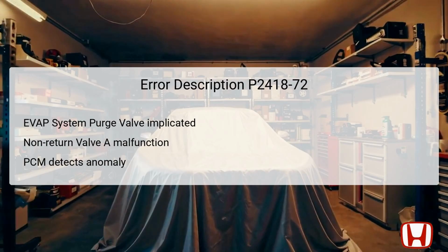If the valve is stuck open, it can create a continuous flow of vapors, signaling an abnormal state to the PCM. The PCM, or Powertrain Control Module, interprets the pressure reading from the ELCM, which is an abbreviation for Evaporative Leak Control Module. When the waveform from the pressure sensor shows an incorrect phase, the PCM triggers the DTC and stores it in memory for diagnosis.